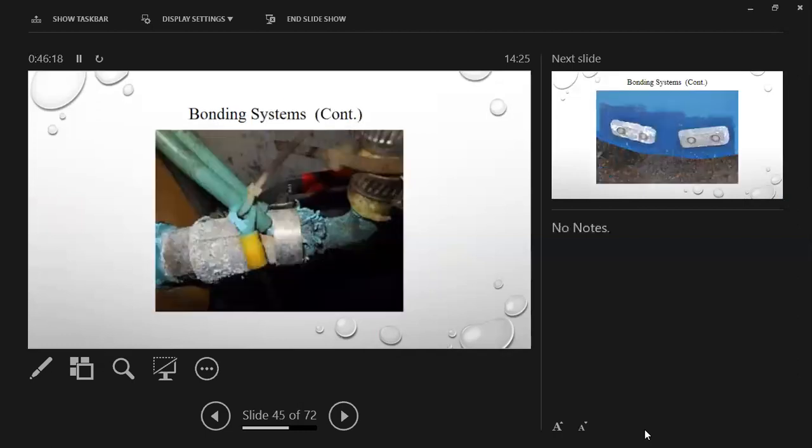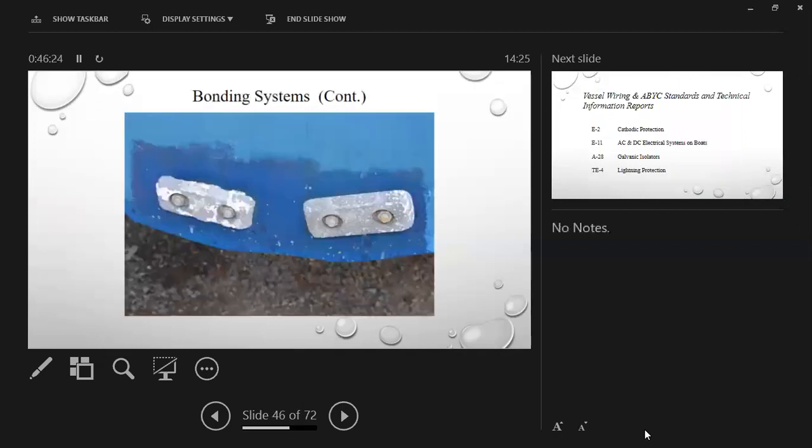Think that bonding system's doing any good? No, corrosion. Perfect. Yeah. And what's wrong with this one? You see something wrong with this? A couple probably zincs, or at least anodes, on the transom of a boat. One's eaten up, one's pretty nice. Wires are broken. I think a bonding wire has broken off of this one.